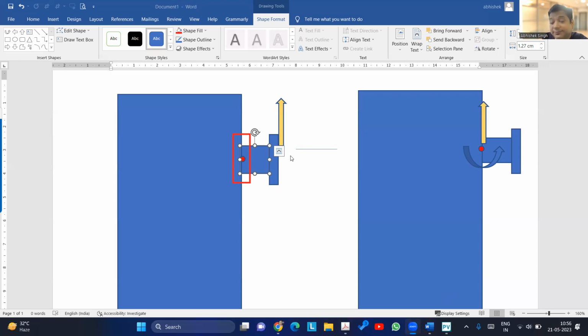On the weld, definitely there will be additional forces. The weld is stronger than the nozzle neck. So basically you have to check the nozzle neck, which we will do. That will be the third part. Right now we are talking about the effect on the flange. Okay. Just concentrate. We are talking about the flange: what will be the effect of these 6 loads?